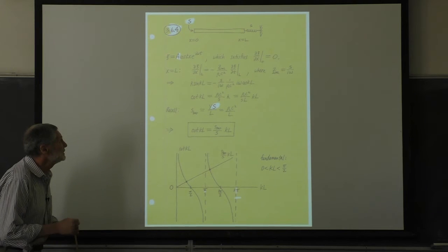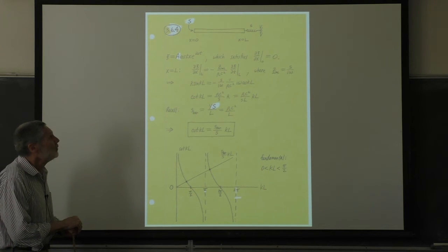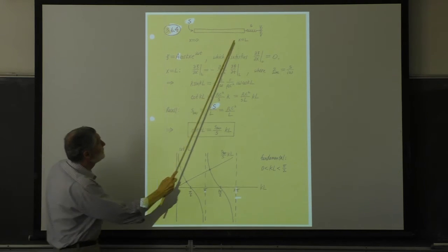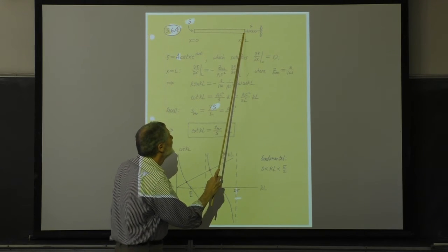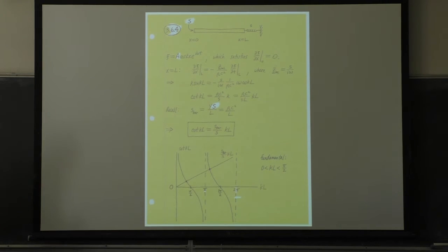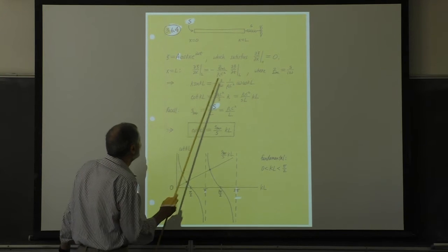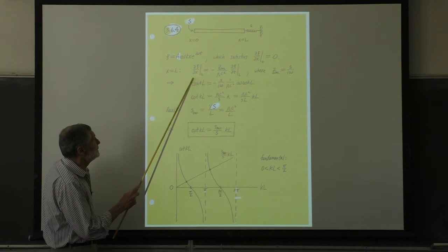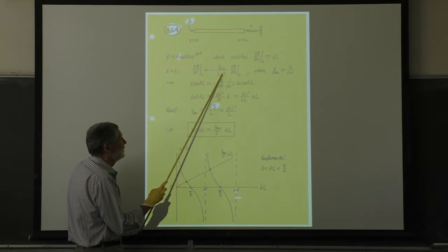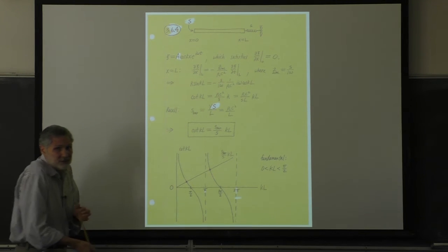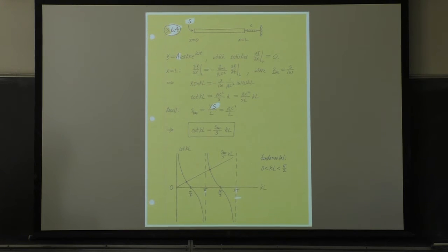Now, what's the boundary condition at x equals L? Well, you can write down Newton's second law. The net force on this face of the bar has to be 0, because otherwise we'd have an infinite acceleration. And this is undergoing simple harmonic motion. This is steady state. So we have to have 0 force. Well, you can do that, but the quicker way is to use this, which we derived in lecture. This works for any terminating impedance, and it's equivalent to Newton's second law.